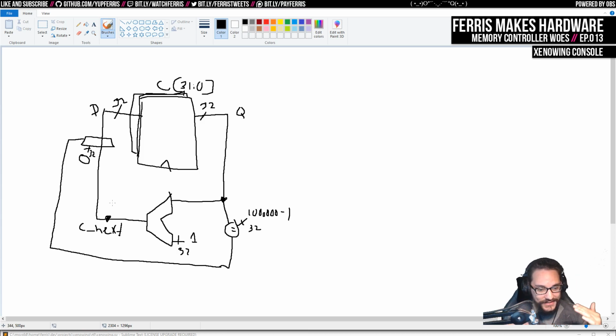But of course it changes the timing relationships, because then suddenly maybe the input to this mux is a shorter line, but then maybe this compare is more expensive, or the fact that this compare happens after this add instead of simultaneously with the add. And I think that's the most important thing here: if you look at the data dependencies, the add and the compare are both inputs to the mux.